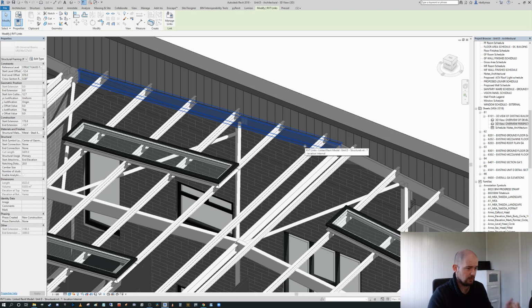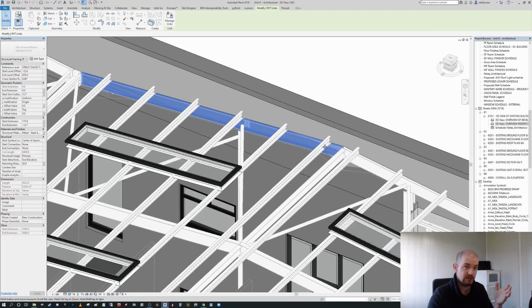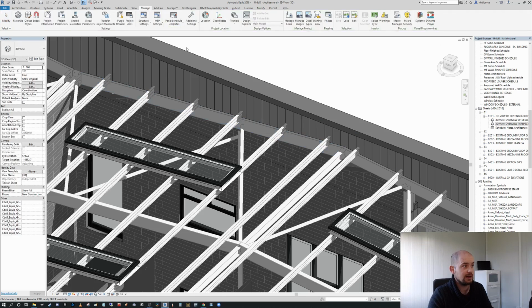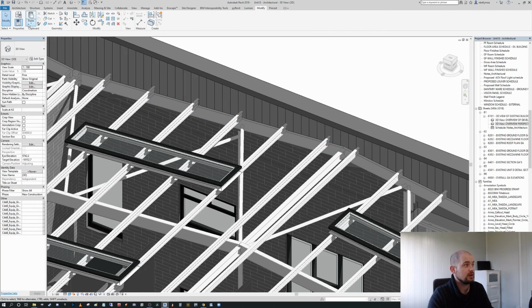Let's say we can't edit the link within the parent model, but let's say we are bringing in a reference file from a subcontractor and they have information in that that's pertinent to your design information. You may want to just take that element into your parent model easily. So let's assume maybe this is a piece of equipment or something like that. We can press Control C to copy to the clipboard, and then we can click off at the space and go into Modify, Paste,